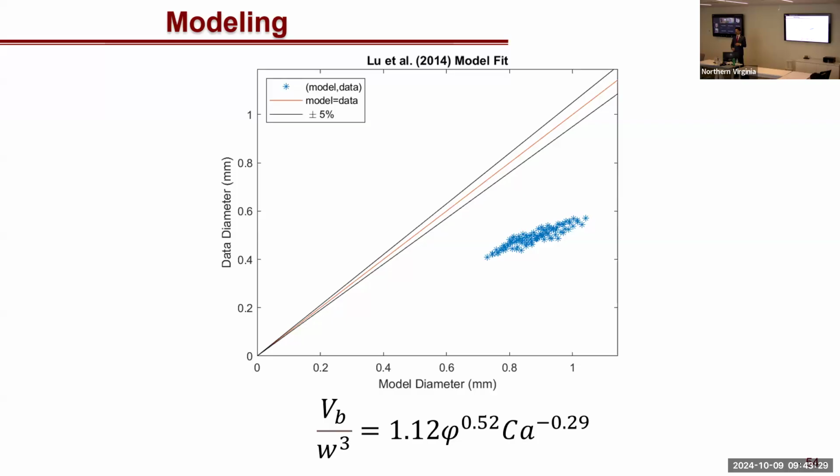We also observed that the pressure drop was greater than would be expected with a square cross-section. Using fasteners to increase the pressure on those microchannels to hold it together and prevent leaks, our hypothesis was that it crushed these microchannels, making them rectangular rather than square.